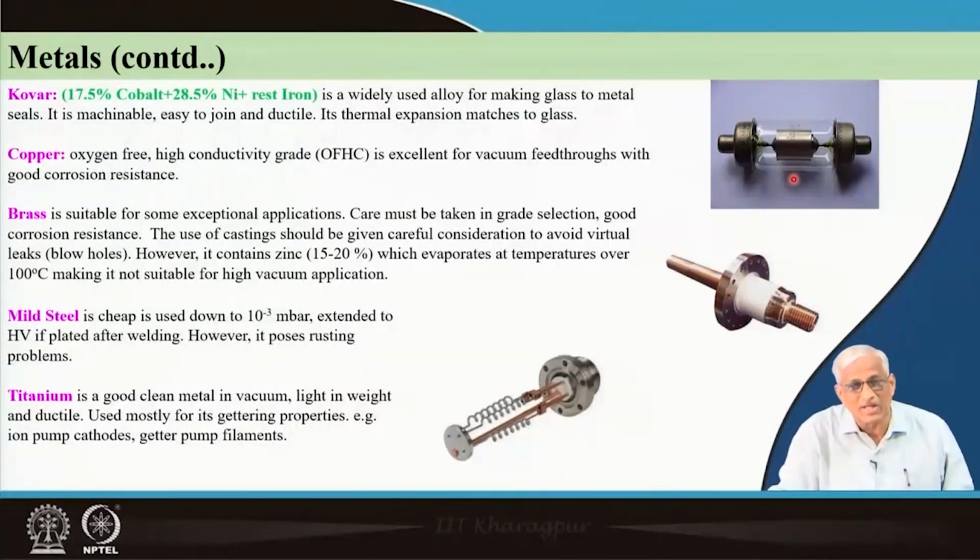Most high power electronic applications still use valve based electronics, triodes, diodes, etc. In such places you have metal to glass joining, which is possible with Kovar because it has matching thermal expansion coefficients with the glass.